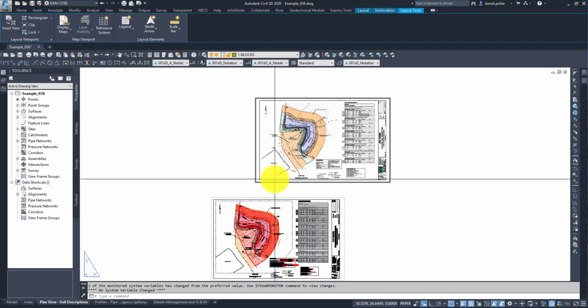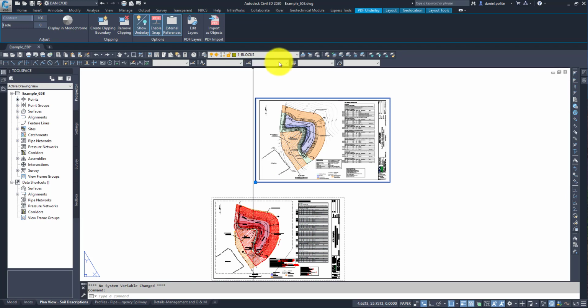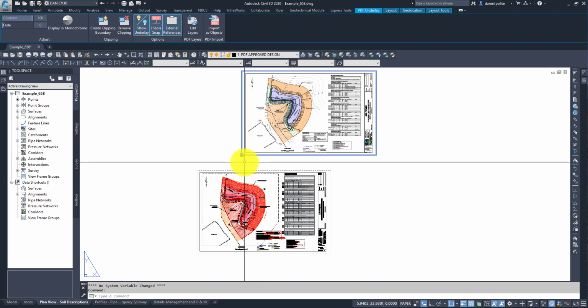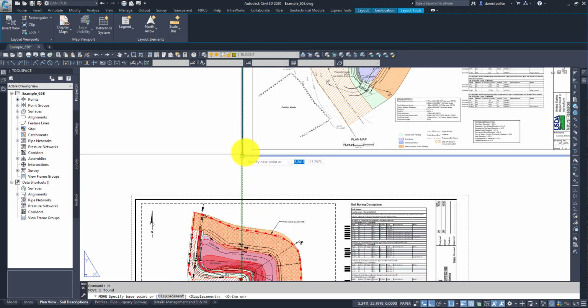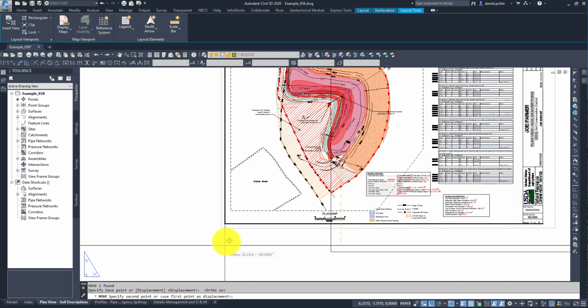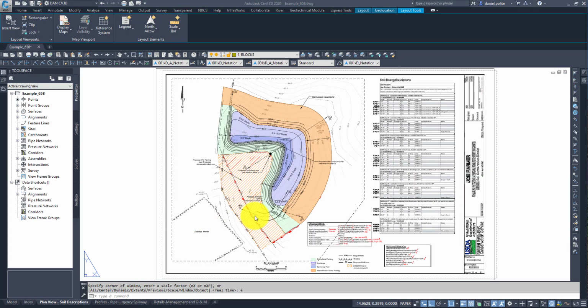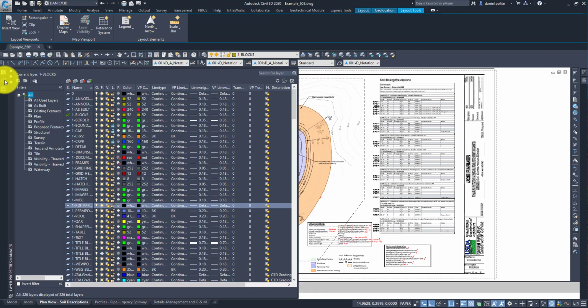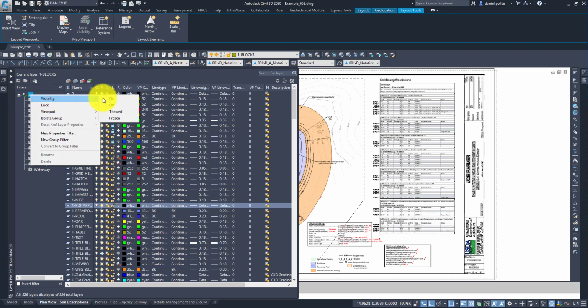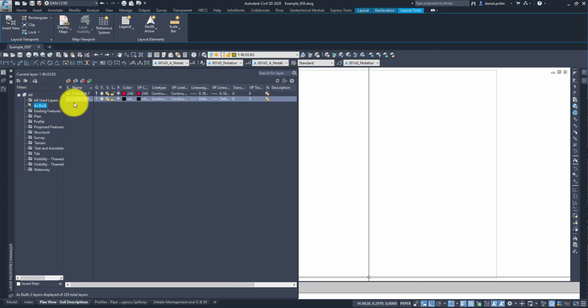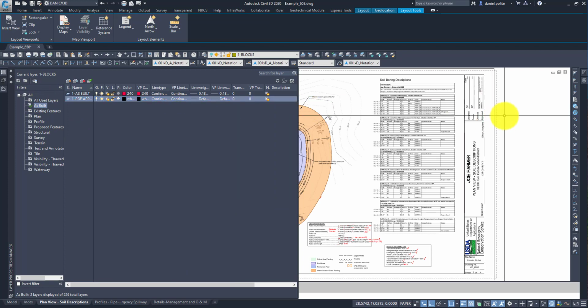and you'll notice that it does it 90 degrees. So you can do it either way. Put this on your PDF design layer. Go ahead and move that. And for move, F8 to turn on your ortho mode. Select your corner, corner, and move it. And again, go back to your layers, right click, visibility off, and then you can go to your as-built and just turn on your PDF and your as-built layers.